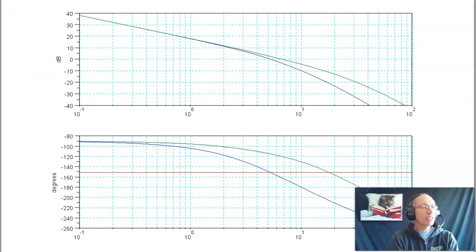I can see that on the Bode plot as well. If I take the original curve, that's the blue line. If I want a 28 degree phase margin, I look at -151, -152 degrees, find out what frequency has a phase shift of -151 degrees. At that frequency, make the gain 1. To add a lead compensator, I've got phase problems at this point.